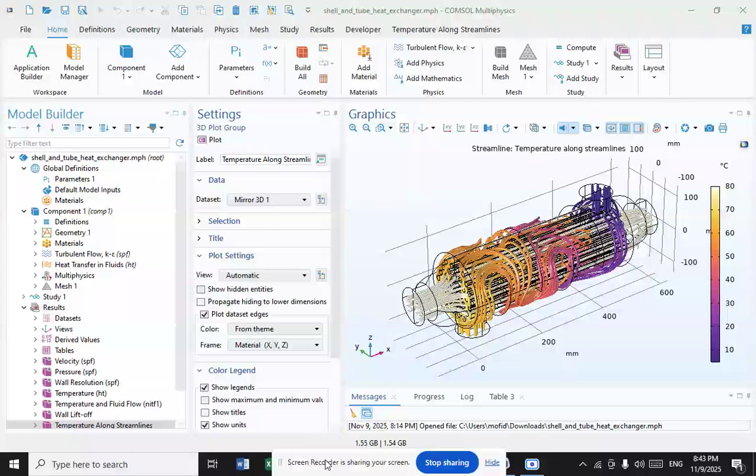The fins are typically made from aluminum or copper since they must conduct heat from the tube along the length of the fins, which are usually very thin. The main construction types of fin tube exchangers are: the first one, a stack of evenly spaced metal plates act as the fins, and the tubes are pressed through pre-cut holes in the fins, with good thermal contact usually being achieved by the formation of the fins around the tube. This is typical construction for HVAC air coils and large refrigeration condensers.